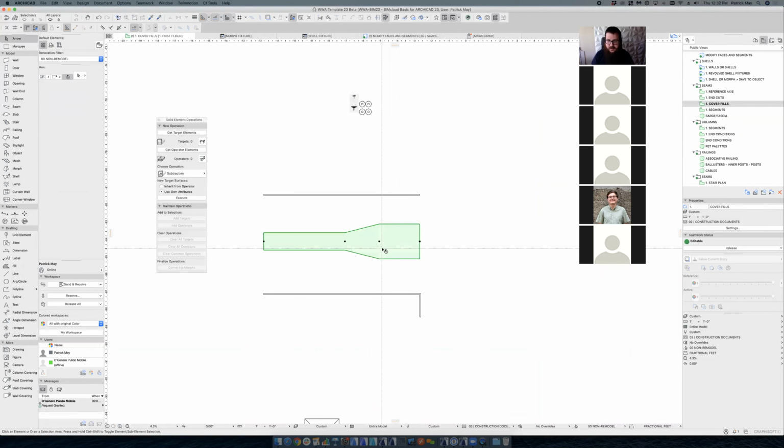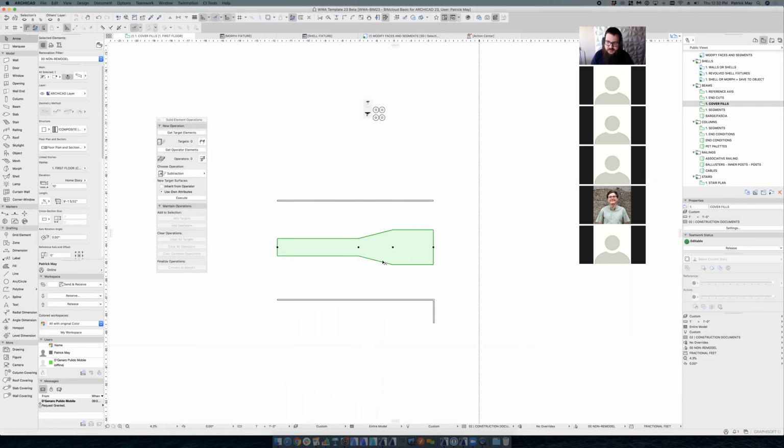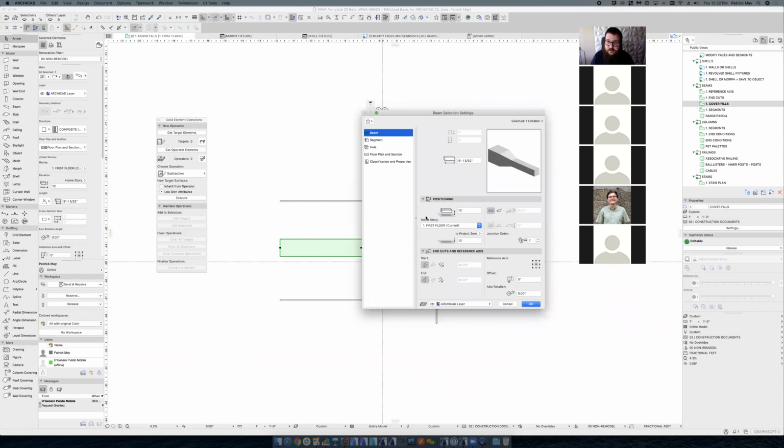Next, beams can have segments. And this one, ArchiCAD likes to showboat a lot of really complex beam and column conditions where they basically model huge moment frame structures with a single beam. It's really tedious and it's a waste of time. You can use 30 elements to model that moment frame and model it in probably 10 minutes, or you can try to do it out of a single beam and probably take 3 days to do it.